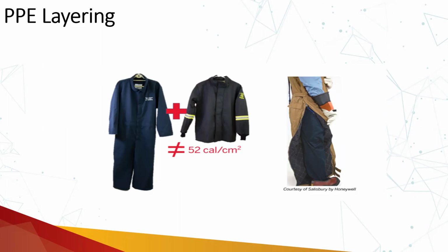Why are you not using digital technologies or remote operations for those locations? Why have those switchgears or normal switching points not been changed to arc resistant switchgear? So personal protective equipment, arc rated clothing, is available above 100 calories per centimeter square.